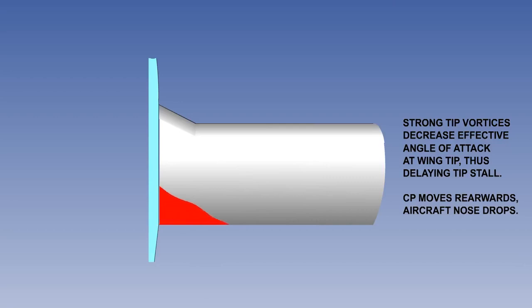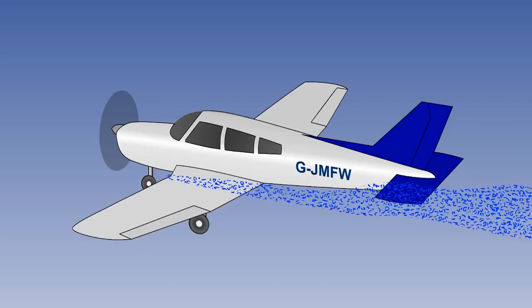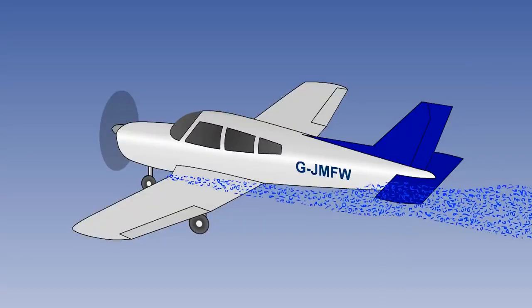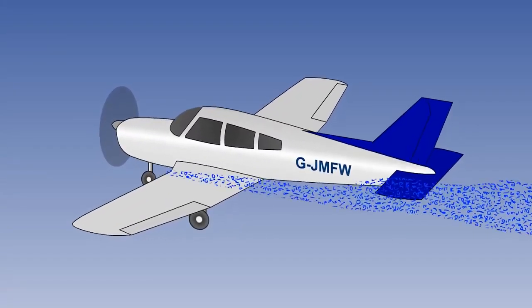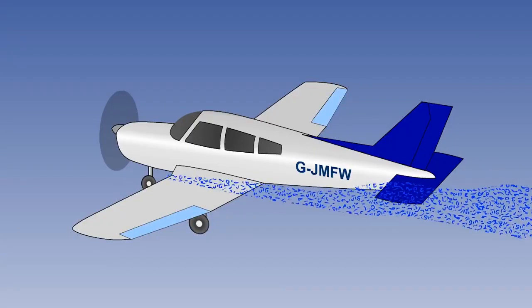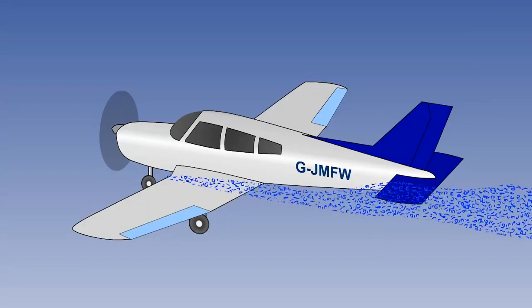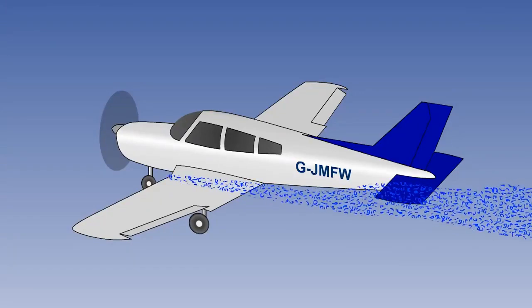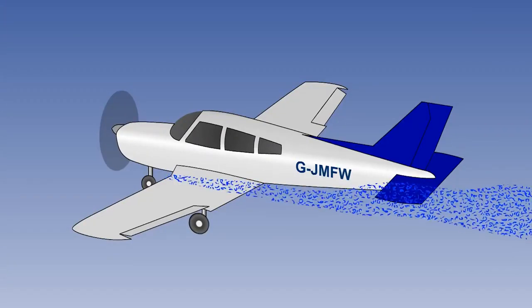As the aircraft stalls, the centre of pressure moves aft, causing the nose to drop, thus reducing the angle of attack. This gives the aircraft a natural tendency towards a recovery from the stall. The separated airflow from the wing root passes over the fuselage and tail unit, and the aerodynamic buffet caused by it can provide a warning of the approaching stall. The ailerons, being located outside the separated flow, will tend to remain effective as the stalling sequence starts. All these factors give the most desirable kind of response to a stall, namely